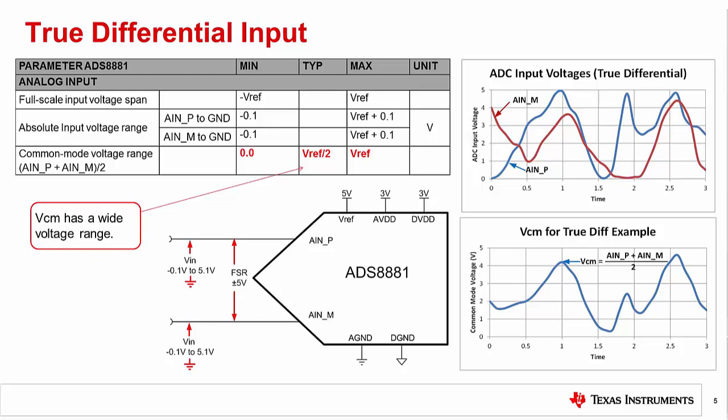This slide covers the true differential input. This ADC input type is very similar to fully differential. The main difference is that a true differential device allows for any common mode voltage within the input range, whereas the fully differential input requires the common mode to be held constant at half of the VREF voltage.